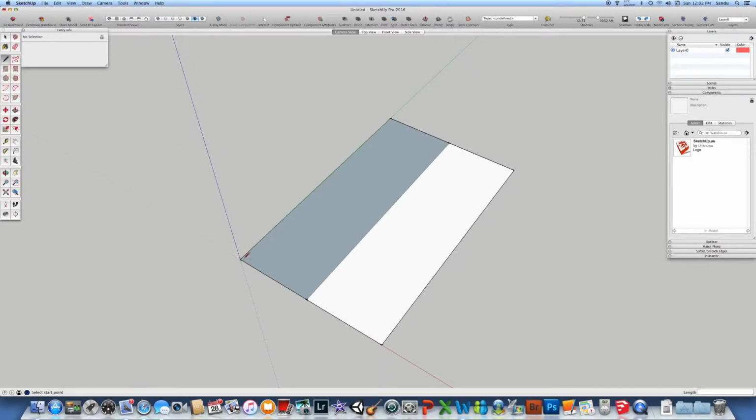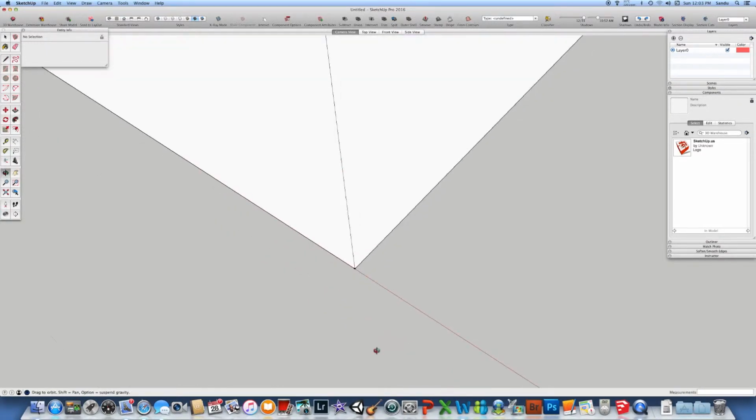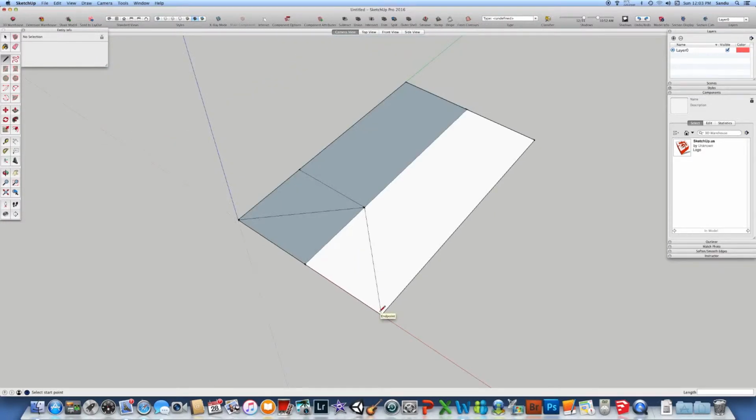Ideally, we should draw a line at 45 degrees, and there are many ways to do it. Either you can draw a line outside and rotate it, or a simple trick is to look at the sign over there. You see that dashed line, that always is going to draw a square. So you can just draw a square, and after that a line from here to here. And we know it's 45 degrees. We know that was at the middle. If I draw it here, I know those lines are at 45 degrees. So basically 45 degrees here, 45 degrees here, therefore I have the roof.